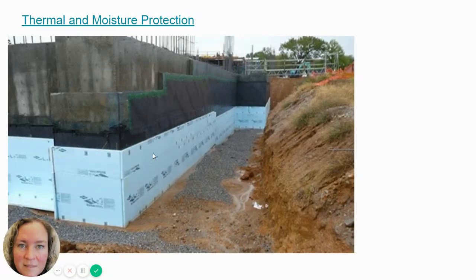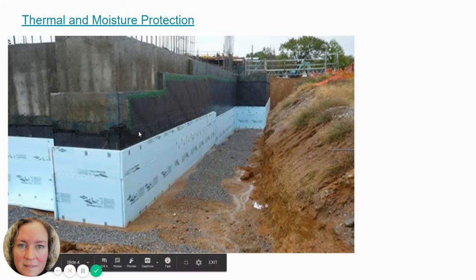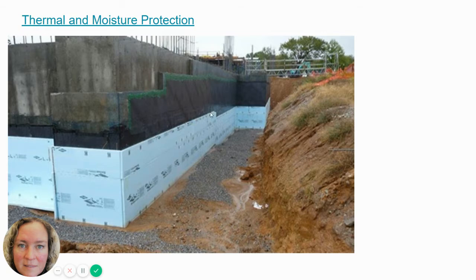And here's an example of thermal and moisture protection in your foundation system. So we've got insulation, all this stuff is going to be backfilled against the foundation wall. And you can see insulation has been placed on the outside up to where grade will be. There would be some more insulation on the inside that will go up to where the floor would be most likely. And then this area here has all been painted with a waterproofing paint that protects the concrete from moisture. Because concrete's extremely porous, and so you've got to make sure you paint all the areas that are going to be exposed to the ground.